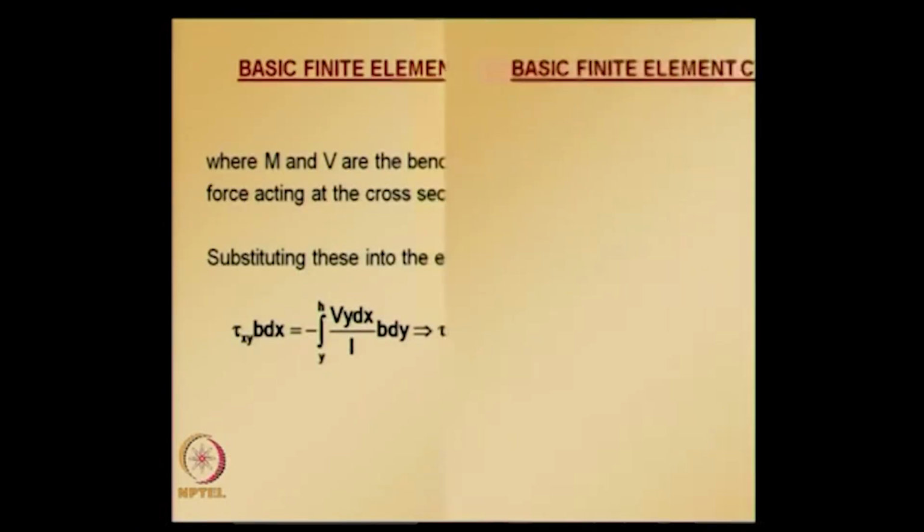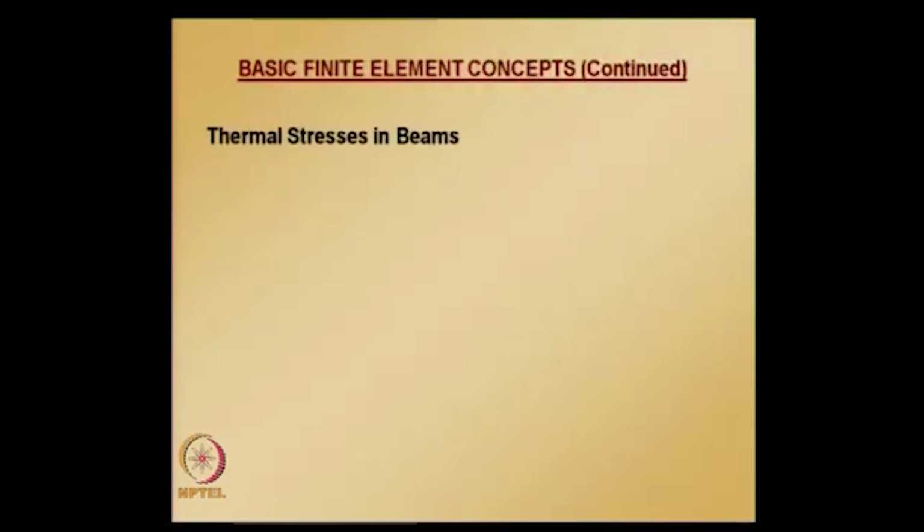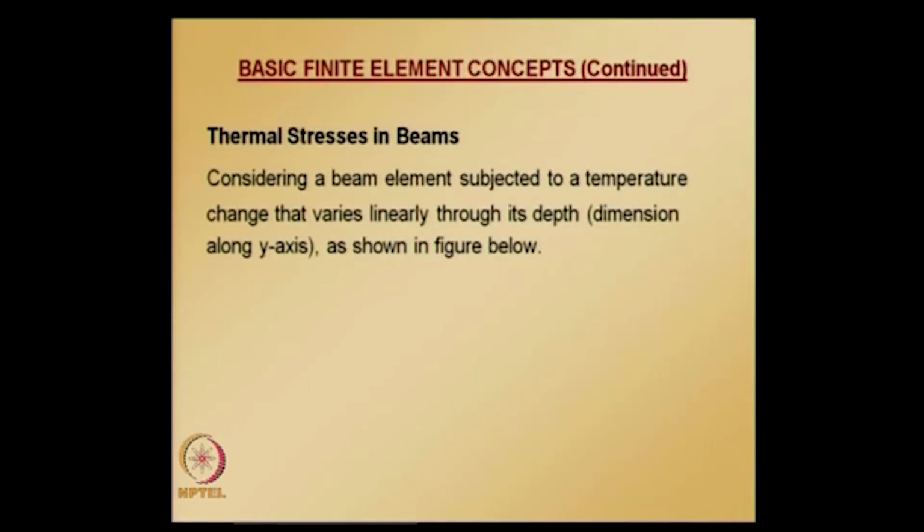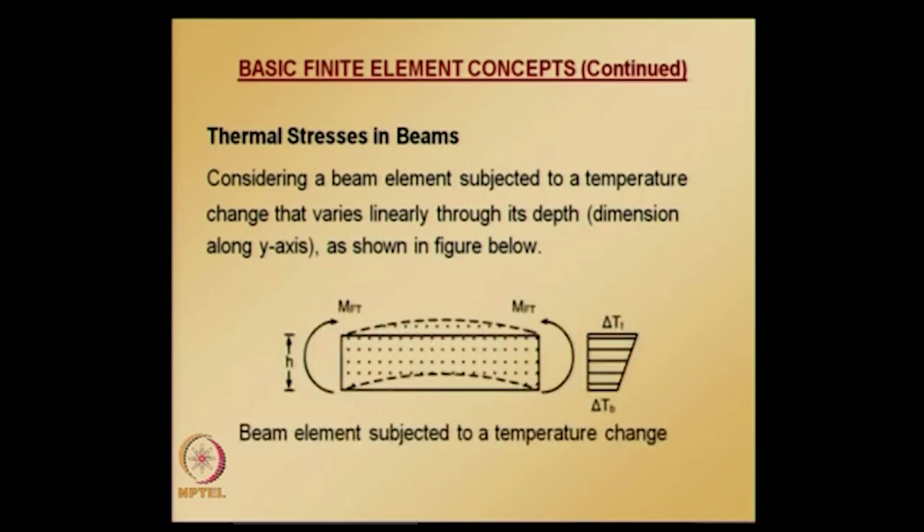Consider a beam element subjected to a temperature change that varies linearly throughout its depth, meaning you have one temperature at the top surface and another temperature at the bottom surface. In this kind of situation the element will experience curvature, because there is a temperature change between the bottom surface and the top surface.